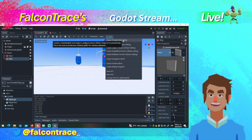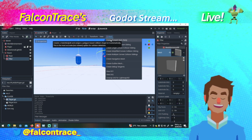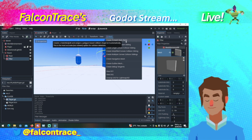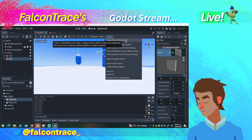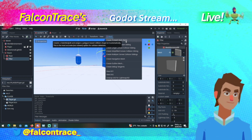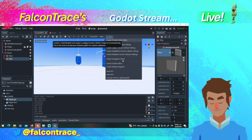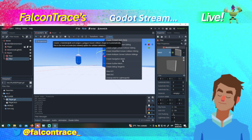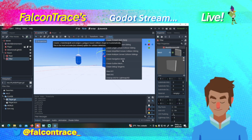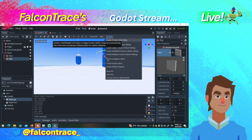The most common one that I use for static objects is this one over here that says create tri-mesh static body. I use it for walls, for floors, stuff like that that isn't going to move. If you want to choose another option depending on the characteristics of the object that you want to make a collision shape of, you can check the tooltips over here.